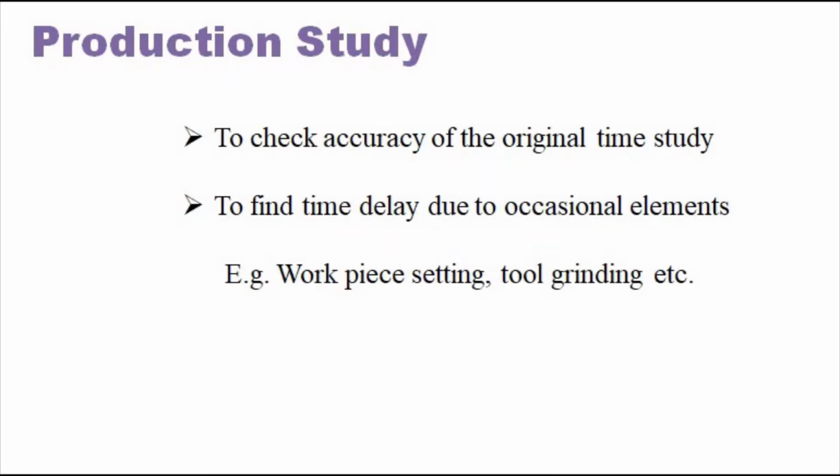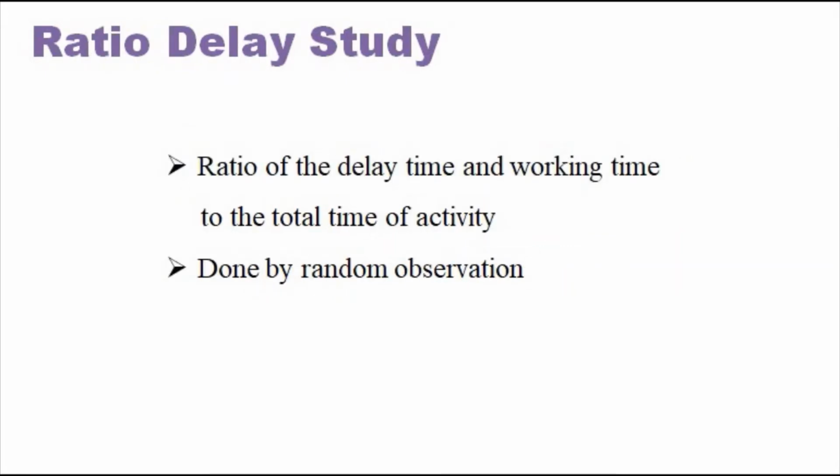These elements are considered in this production study. It will check the accuracy of the standard time which we received through the stopwatch study, by considering all the time required for the occasional elements also. So this is like checking the accuracy of the standard time.